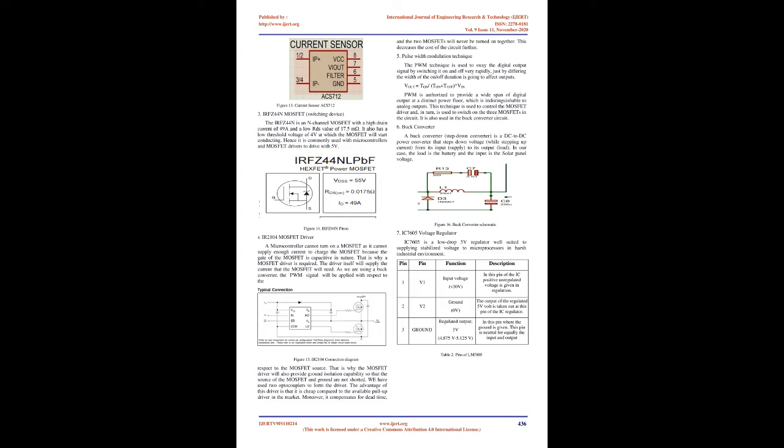When the width is at 100%, the transistor is at full on, allowing the solar array to bulk charge the battery. When the width is at 0%, the transistor is off, open circuiting the array, preventing any current from flowing to the battery when the battery is fully charged. Like the series regulator, the transistor can be placed in either the positive or negative line, allowing the regulator to be used in positive and negative ground systems.